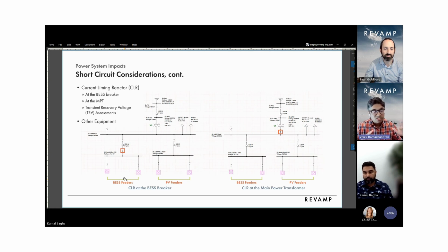Now, let's assume the NGR is properly sized and the ground fault current constraints are taken care of. We are still left with the phase fault currents to deal with. And we can look at a couple of different scenarios. One scenario where, due to the proximity of the BESS to the substation, it's just the BESS system where the phase fault currents are exceeding tolerable limits.